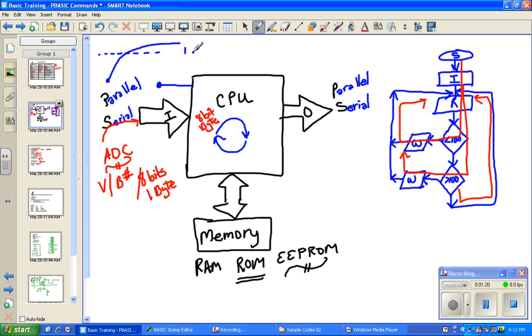We know that 1.4 volts is the voltage threshold for this microcontroller. So we're going to initialize the circuit at 0 volts, and then the microcontroller is going to determine how long it takes for that voltage to reach 1.4 volts. That time will then be saved into the microcontroller as a variable that represents the time for the different resistance that's connected to the capacitor.